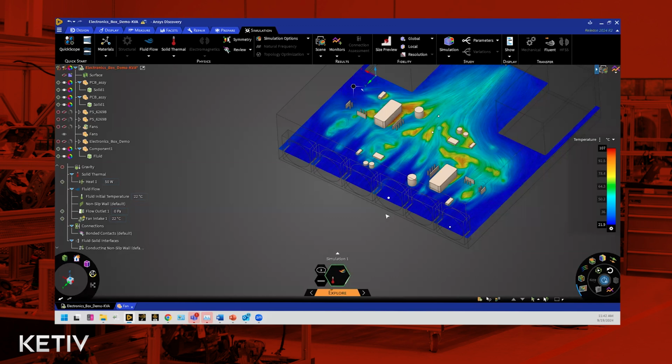And what that meant was sometimes if you had a wide range of characteristic lengths in your geometry, with the smaller features being extremely small, even if you shifted the fidelity bar to the extreme right, you wouldn't be able to resolve them. Okay, so now, Discovery has the flexibility of allowing you to assign local sizing even in the Explore stage while you're using the GPU.